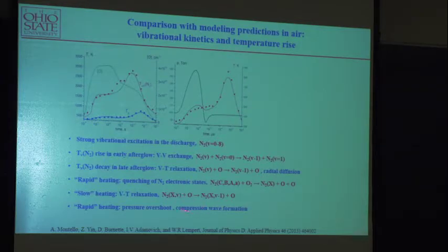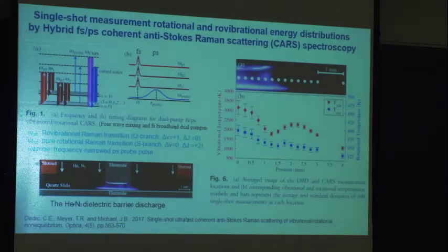So therefore, these reactions, for example the nitrogen ABC electronic excitation, are very important because they directly collide with oxygen and give you radicals. The first thing you need to consider is this, and then this is probably the second-order thing you want to consider in the combustion process, because the process is quite slow. You can see it takes about 10 to the minus 2. And the non-equilibrium effect is not really that strong in terms of kinetic effect. Okay, so let's move on.